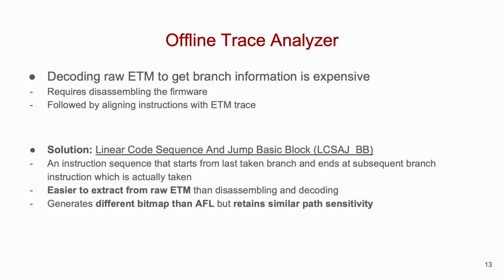Finally, ARM supports streaming the trace data to an external debugger via a physical parallel port called Cortex Debug plus ETM connector, which is what mAFL opts for. Additionally, mAFL transmits the subsequent test case in the background while the target is running against the current test case. They further conduct the analysis of the previous test case on the host in parallel with the target execution. By scheduling all these tasks in a pipeline, mAFL achieves optimized performance.